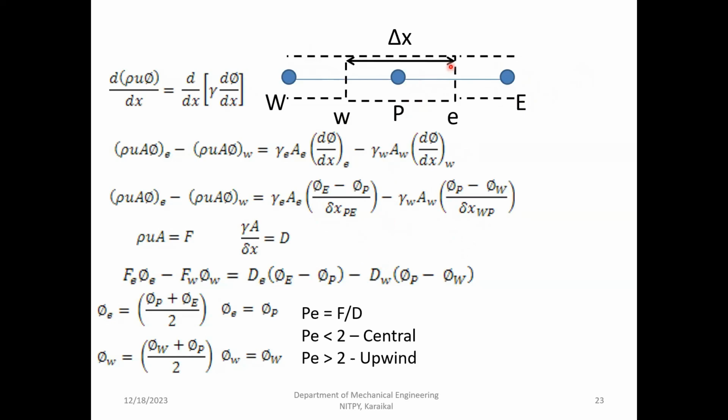If you have a normal diffusion problem, you can go with central differencing. If you have high-speed flows, generally you'll go for QUICK schemes. So this also must be selected when you choose in Fluent. This is another method: you can take 3 points upstream, and then solve it.